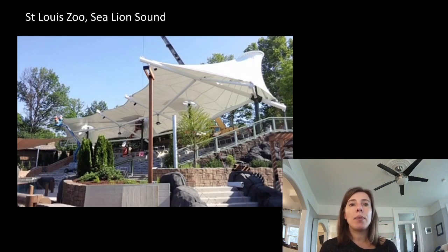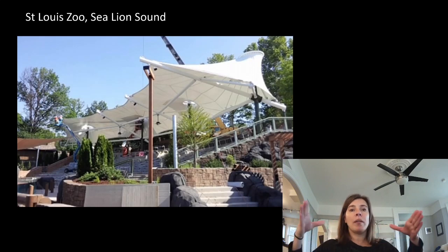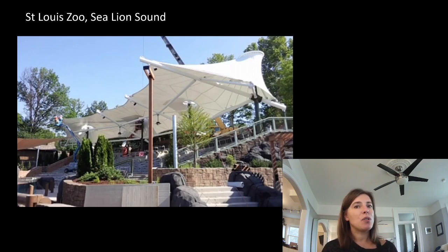And we need to be able to tell people how much those things need to stretch, because we literally pull them into our shape. And you can imagine that the amount you can pull it, if you remember your stress and strain equations, varies on force and the stiffness of the material. And Dave talked 2 weeks ago about warp and weft and how the material behaves differently in 2 different directions.